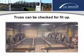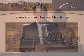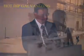Some states require that before it's ever shipped to the job site, actually before you put any finish on it. And speaking of finish, you can also do the 3-coat paint systems right in the shop, then ship it to the site and do the final touch-up after the bridge is erected.